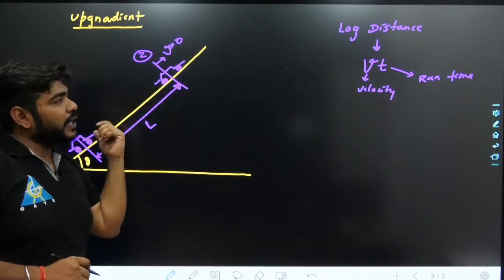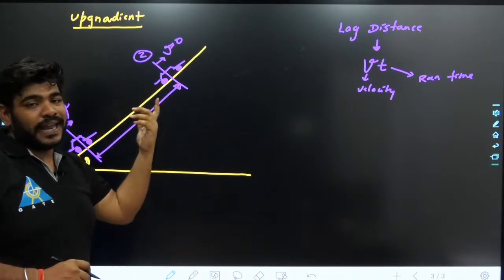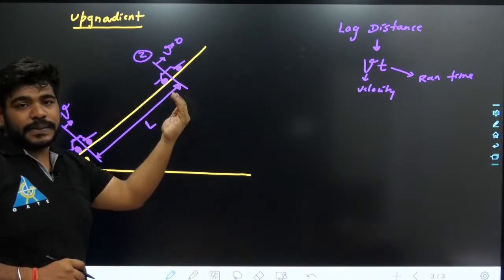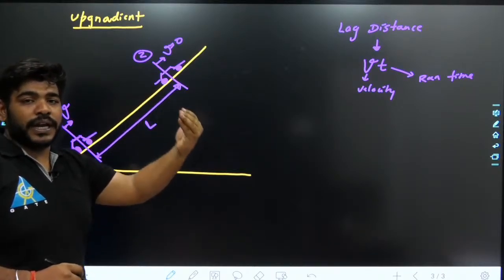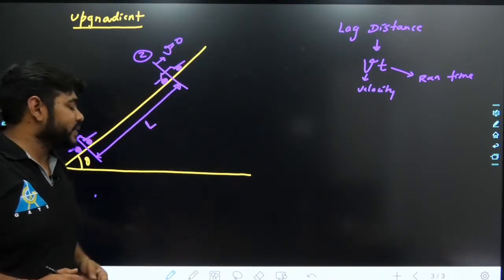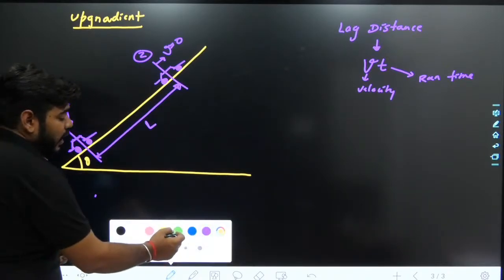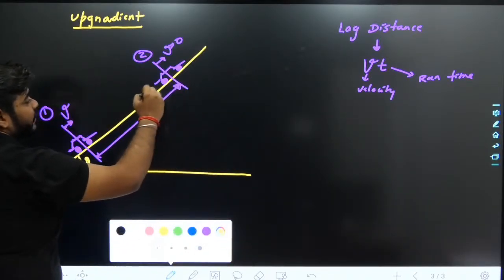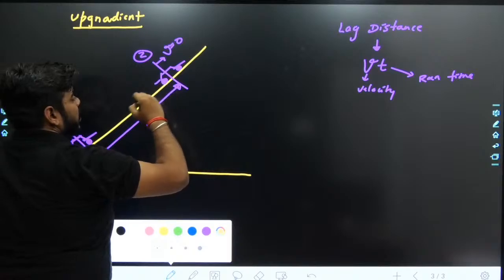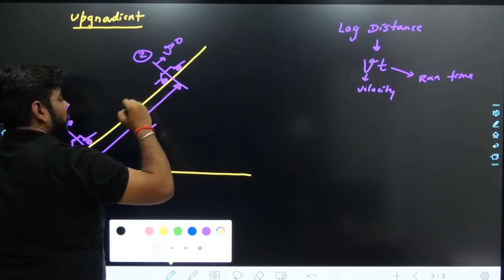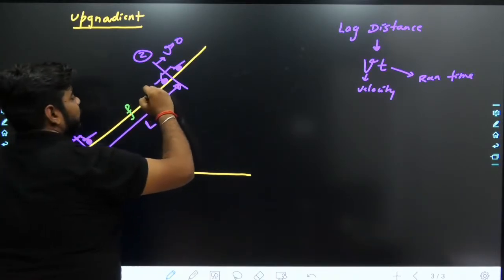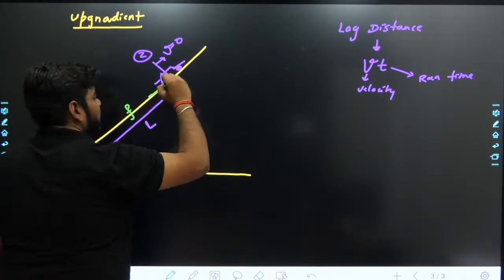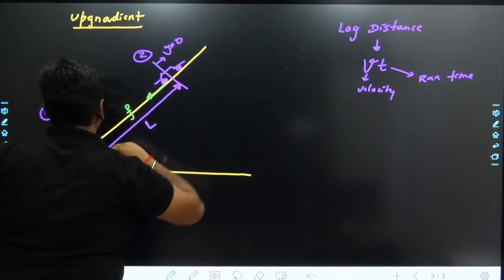So what is happening here? We will apply the work-energy principle, and you'll see the whole kinetic energy is converting into work done. The coefficient of friction for this particular pavement is given as f. If somebody talks about the frictional force that is acting on this pavement,